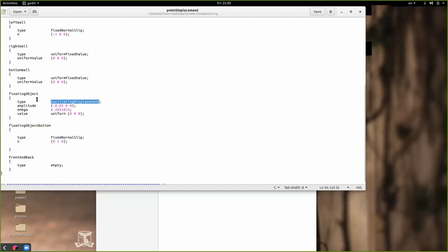And for the case of the floating object, we prescribe the motion, and look, this time the amplitude comes over here. Yeah, this is the x direction. So we have the motion in x direction, not z direction. You can have the mixture, but I'm sure the simulation will crash if we do it at the same time because we haven't done the setup for such a problem.